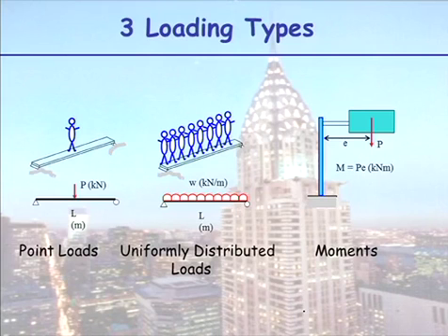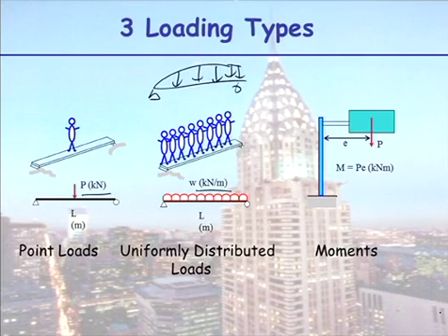So let's now work our way from the beginning. These mathematical models we learnt about are theoretical models. So when we look at reality, we then have to say, how do we apply that loading? And we learnt that we either apply the loading as a UDL load, as a point load, or as a moment. Now, this UDL load can, of course, have other forms. It can be some sort of linearly varying load. And we did a little bit on that. But primarily, we limited ourselves to a uniformly distributed load, a load of units kilonewton per metre, or a point load, or an applied moment. So these are our theoretical loads.